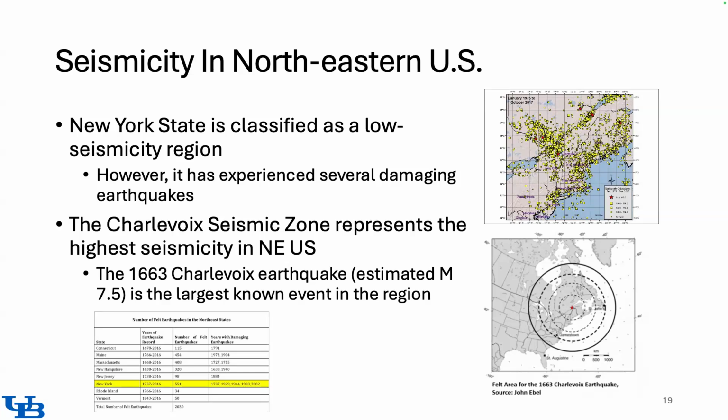Cracks are more common on the West Coast, and the rocks here are more solid, right? Exactly, yes. Here we have granite, which has a shear wave velocity of 2,000 to 3,000 meters per second. It's a much stiffer rock, and also it hasn't been sheared because the seismicity is very low. So when you have an earthquake, which will not happen very often, seismic waves will travel longer.